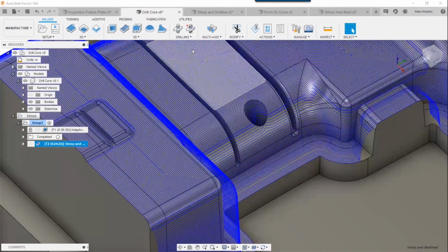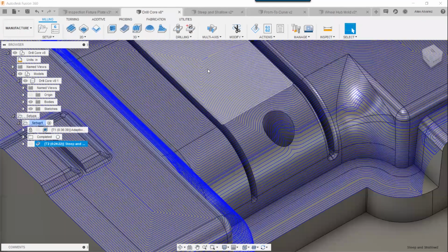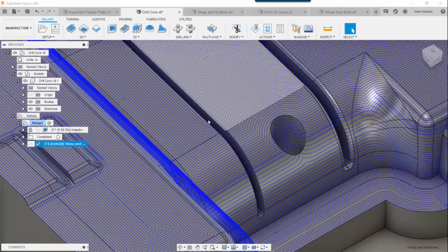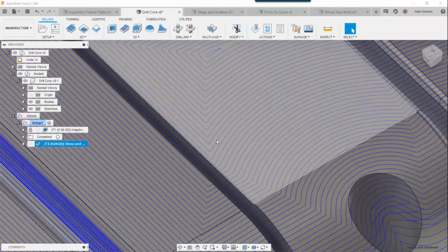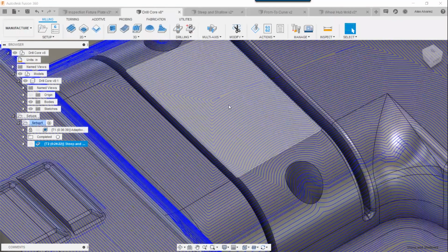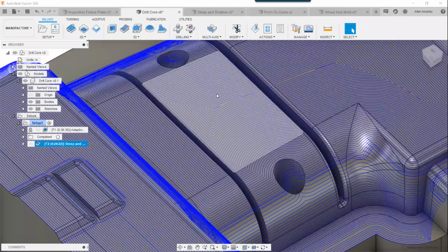What you'll see here is that this toolpath has a couple of sharp edges, here and there. With sharp intersections, the machine is going to slow down quite a bit to match that toolpath, and it's going to start leaving small little cuts when you get to that section.